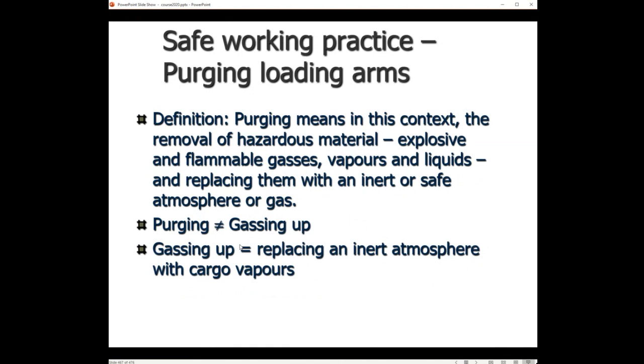But before you start the loading or discharging operation, you can also do a check of the loading arms, and you can check whether the loading arms are well gas tight connected. With the purging of loading arms, we mean in fact after the operations, before we disconnect it, so that the disconnection can take place in all safety. That's why we call it purging.